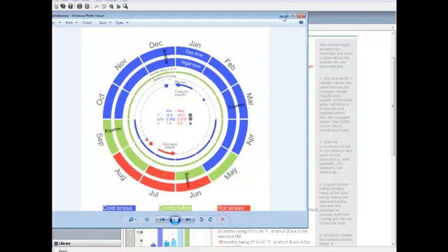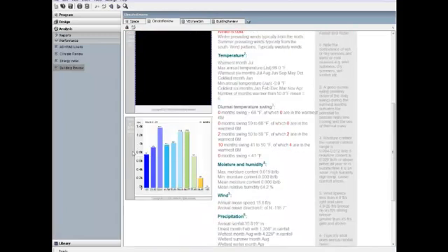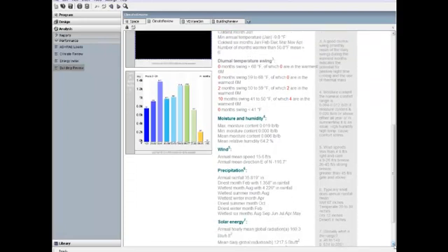Now let's return to the full analysis and take a look at the third graph. This graph depicts temperature distribution, which makes it easy to see which temperature ranges are the most prevalent. The results of this analysis are used in subsequent VE analyses, and the information is used to guide requirements for the building. For instance, we may want to specify that the design needs to contain more transparent surfaces to allow heat in. I can set this as a requirement for the building in the Affinity program.